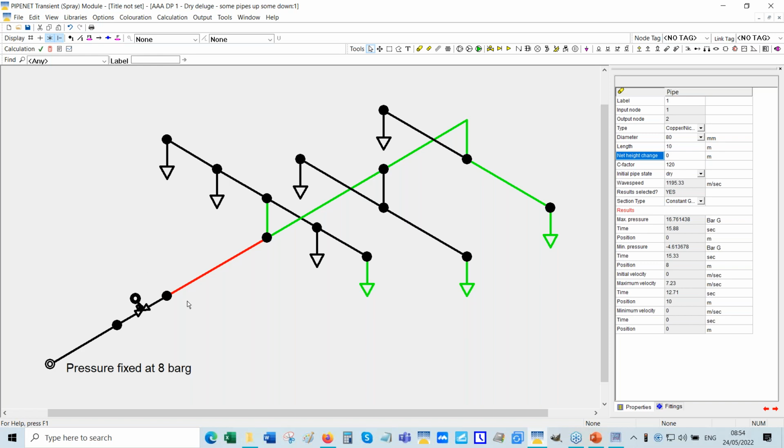And that meant, you see, it took a very long time for that pipe alone to get primed. Once this pipe gets primed, of course, the deluge system discharged very quickly. You cannot change the position of the deluge system. So the only way you can truly solve, only two ways, I suppose, is to move the deluge valve to a higher level.